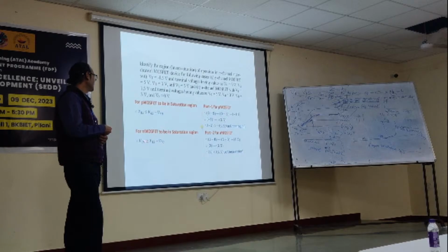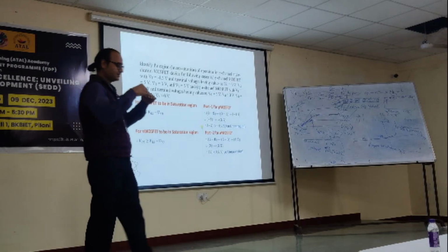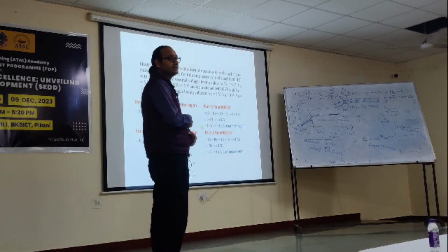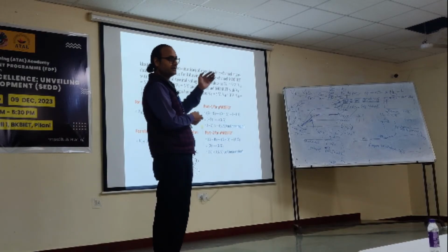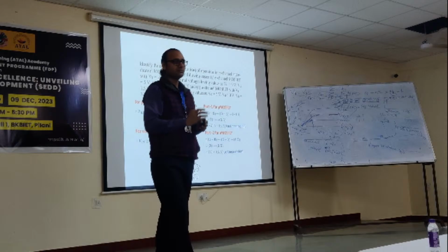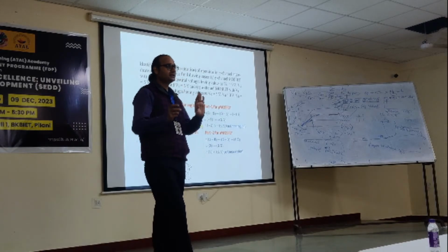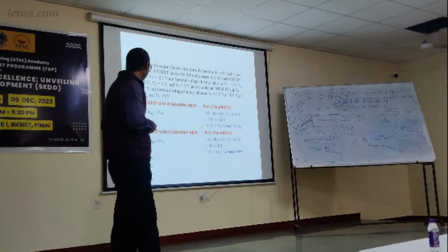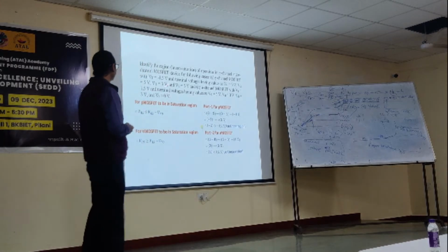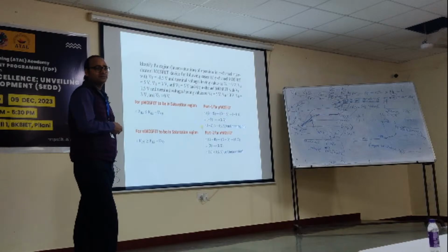Okay. Let me talk about this n channel MOSFET only. Otherwise it becomes very complicated. There we have to think from the negative perspective. If in n type VDS has to be greater, then in p type it has to be smaller. So what you do is just replace everything by its modulus value. Then it will make sense. It means the magnitude of this should be greater than the magnitude of this. That's it. In p channel also, right? Okay. So I think these are simple problems.